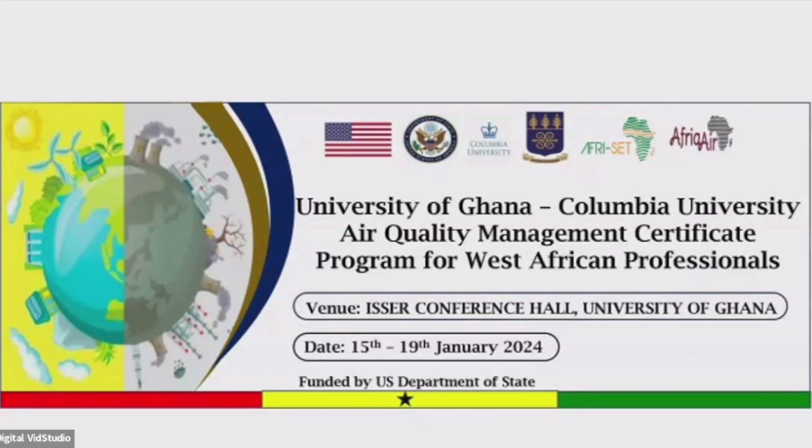Longevity. Gas sensors typically have a lifetime of about 1 to 2 years, but the particulate matter sensors might last somewhere around the 3 to 5 year mark. Whereas for regulatory grade monitors, the instrument itself is expected to last over a decade, assuming you're doing the proper maintenance and replacement of parts.